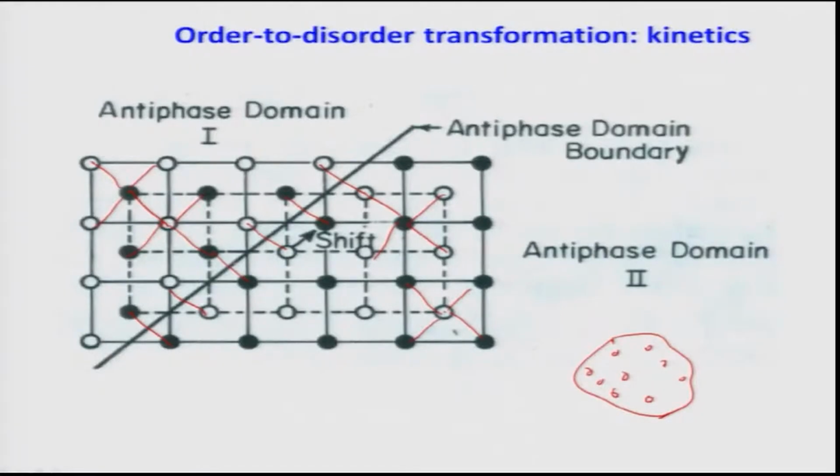How can we do that? You can very easily see this copper-gold atom which is sitting here should have been a copper atom, then the bonding would have been opposite, or this copper atom should have been a gold atom, then this bonding would have been copper. That has not happened. So we can talk about an atomic displacement. Crystallographically the atomic displacement will be a/2 <1 bar 1 1>, and this happens mostly on 110 planes. That can be seen from the crystal structure; that's why the displacement is happening.